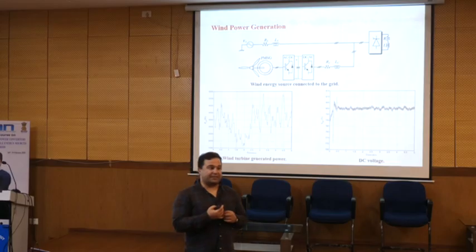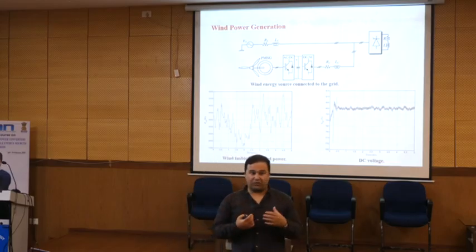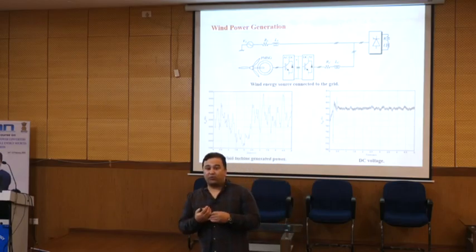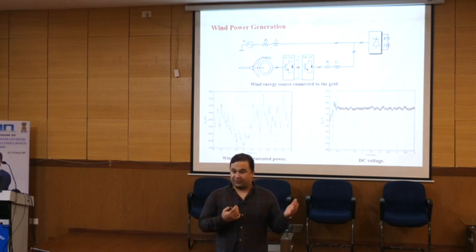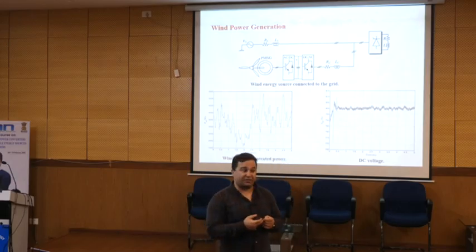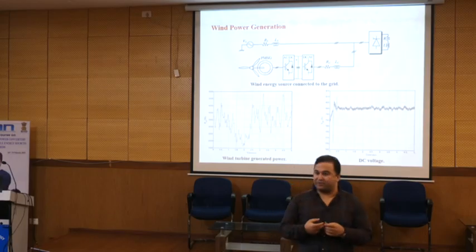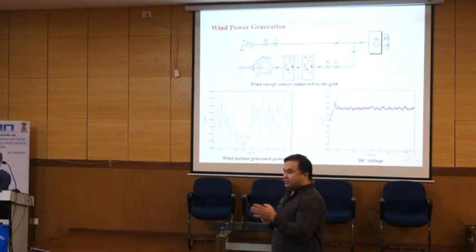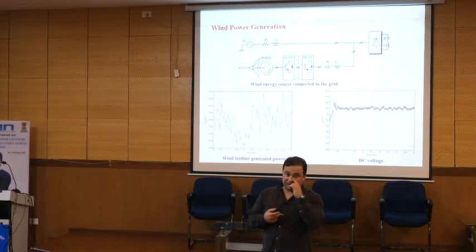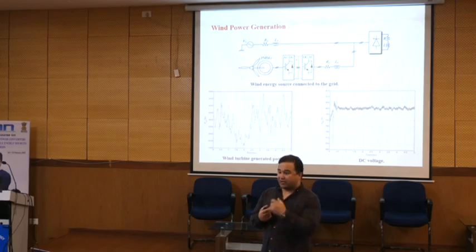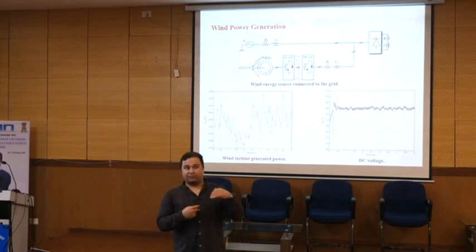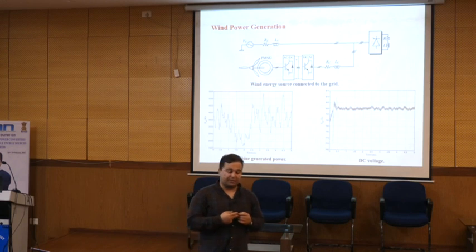Okay, the answer is that this type of technology, converter-based technology, we call it custom power technology, is designed for the distribution level. So these are not components for transmission. For transmission, we have different technology: the flexible AC transmission system, FACTS devices. So the components for transmission are different from distribution. So you cannot say, I'm going to provide electricity and connect it to the transmission line.